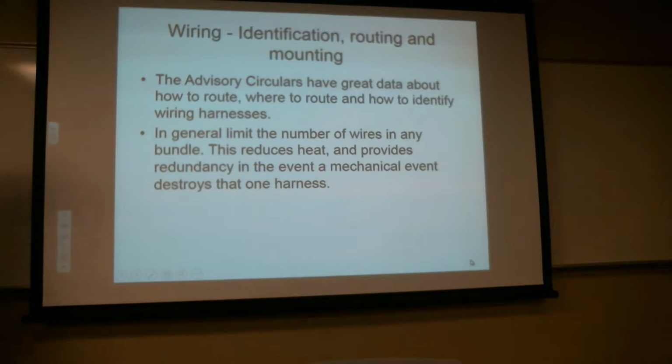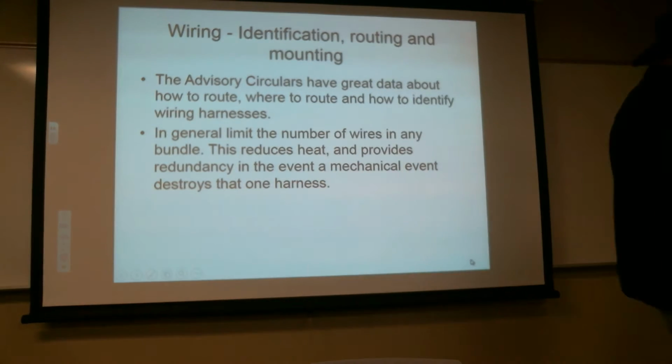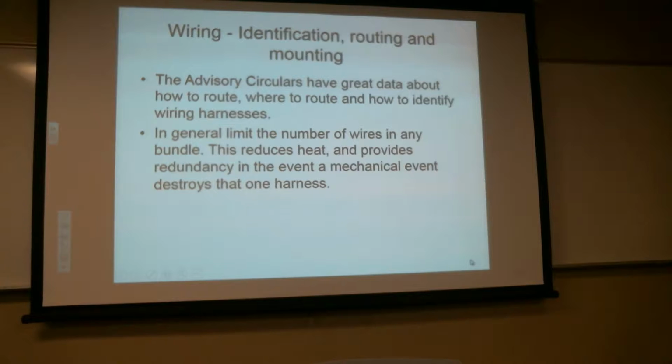Within the 43.13B, there are several charts that specify wiring requirements based upon allowable voltage drop and the length of the wire versus the amount of current being carried through it. From that chart, you determine where you end up on it, and then the next largest size wire, using the American wire gauge, is the wire you want to use. However, there are multiple scenarios. The wire could be freestanding all by itself, it could be in a big bundle, it could be in a conduit, or it could be in a very hot environment. So you may have to calculate or calibrate for temperature.